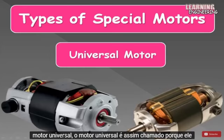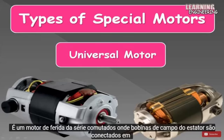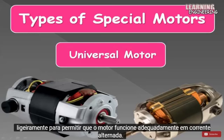Universal motor. The universal motor is so named because it is a type of electric motor that can operate on AC or DC power. It is a commutated series wound motor where the stator's field coils are connected in series with the rotor windings through a commutator. It is often referred to as an AC series motor. The universal motor is very similar to a DC series motor in construction, but is modified slightly to allow the motor to operate properly on AC power.